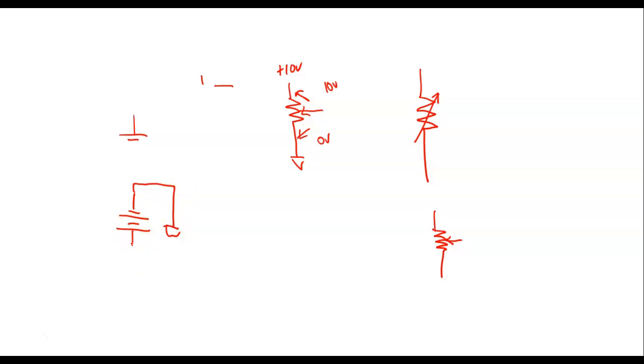I'm going to come over here, and I'm going to adjust this to something more voltage than I need. So I think the maximum we need would probably be around plus 5 volts. Then what I'm going to do is I'm going to come down here and connect this to a 10K pot. Then I'm going to take the output of the potentiometer and I'm going to hook it up to my 330 ohm resistor. Then I'm going to come over here and my diode is going to be forward biased, right?